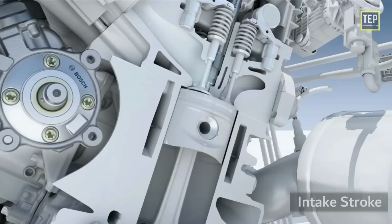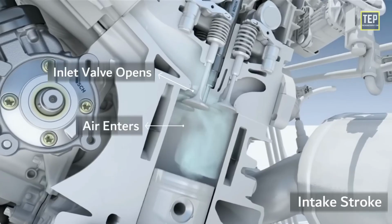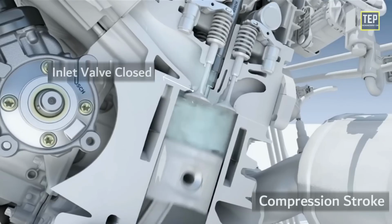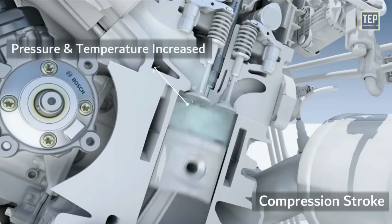Intake stroke. In the intake stroke, the piston moves down, the inlet valve is open, which allows air to enter the cylinder and fills the space. Then the piston reaches the bottom center and again starts moving up. Compression stroke. The piston starts moving up, the inlet valve is closed, then the air is compressed. The pressure and temperature of the air increase due to compression.